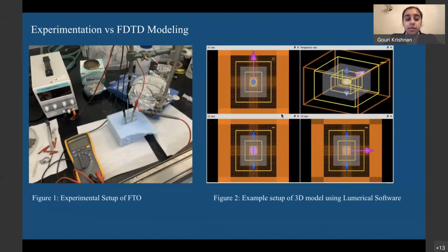For our in-person experimentation, again, the setup shown here to the left, 3 separate designs for the original working electrochromic layer were tested, with the performance of titanium chromium oxide on silicon iridium, on FTO, or fluorine-doped tin oxide, and ITO, or indium-doped tin oxide, being observed, though only the first 2 of these were deemed successful enough to attempt modeling simulations with. Our titanium chromium oxide thin film of 155 nanometers was grown on each of the 3 substrates using ALD, or atomic layer deposition, to ensure even thickness and conformity of thin film to substrate.